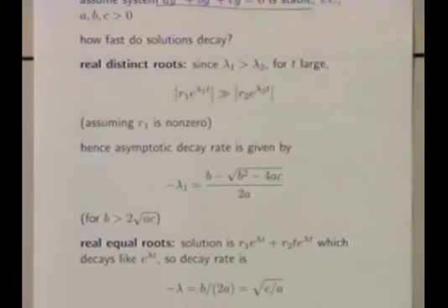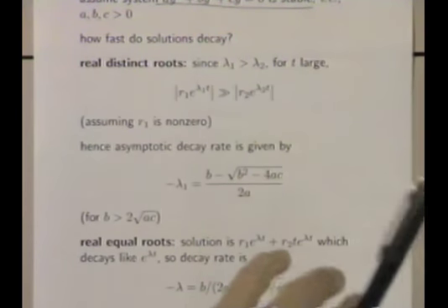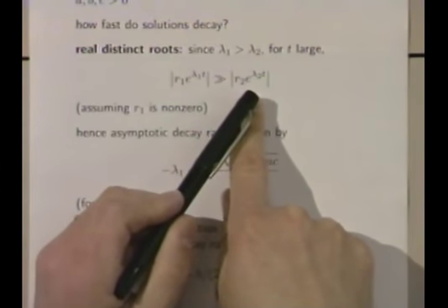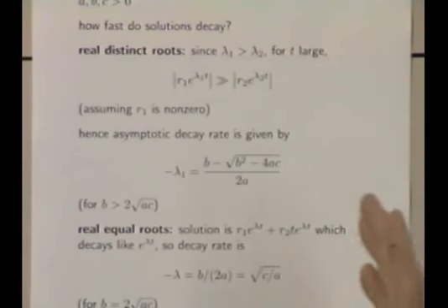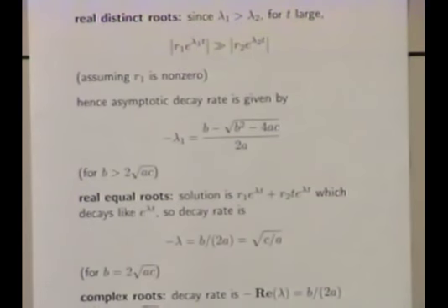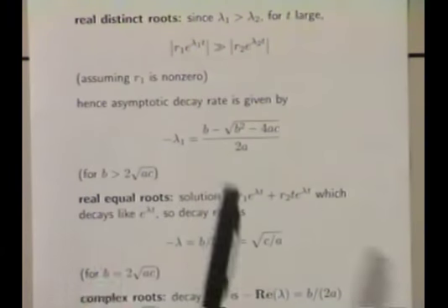We saw an example of that already, that RC-RC circuit, where, basically, very quickly, the smaller one, the one with smaller frequency or more negative frequency, decayed rapidly, leaving you just with the second one. And it looked just like a first-order system then. And yet, lambda 1 determines it.